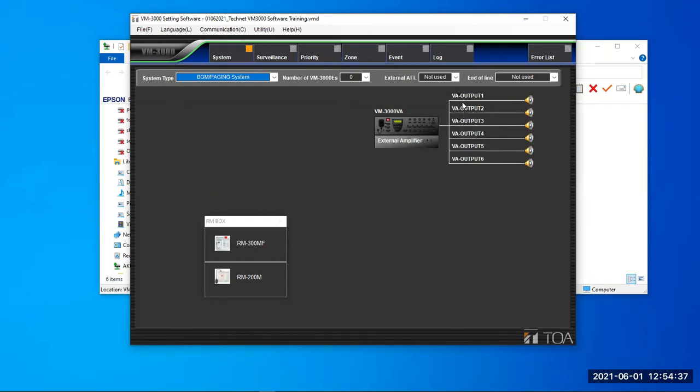If we talk of the Tower SX2000, which is a 16-bus system that we normally deploy at airports, I can have 16 microphones, for example, talking to 16 zones at any given time because there are 16 buses available for that system. This is what we mean by the bus topology when we refer to amplifiers. Is it clear, Patricia? Yes, very clear. Thank you.